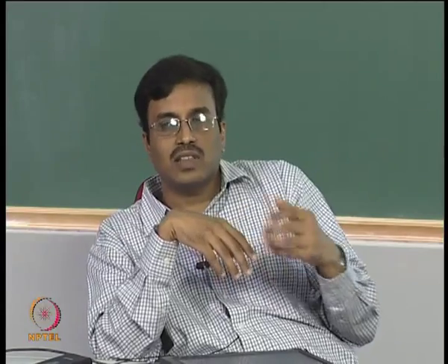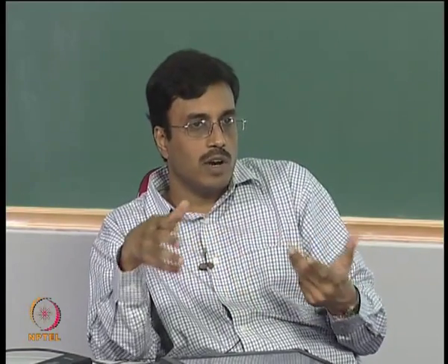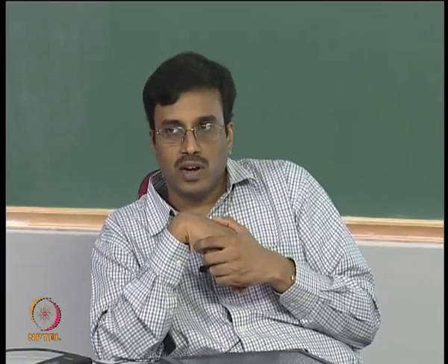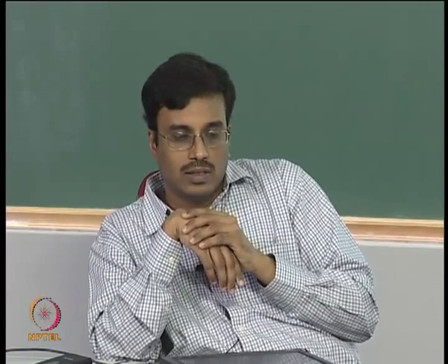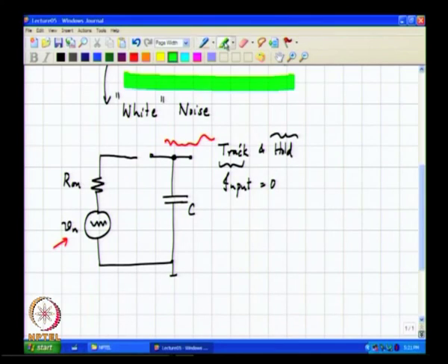Alright. And given that the average of the input is 0, can you comment on the average of the noise component which is stored on the capacitor? The average value of the resistive noise is 0, correct. Now, first of all, why does this make physical sense? Or does it sound strange that the average value of Vn is 0, or it is not strange at all and this is in fact what you must expect?